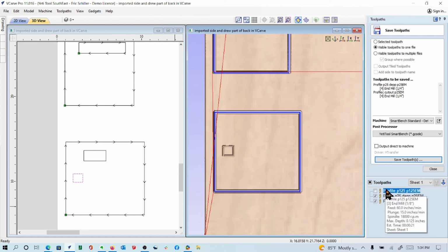So we'd have, just typically for a cabinet, drilling operations with the 5mm drill first, and then we do, depending on how we're building, the same 5mm drill for construction holes if we're going to do a screwed together cabinet, or if we're doing blind dados, we're going to switch tools, go to a bigger tool and use it for the dados and to make the tenons and to make the perimeter of the parts as well, the cutout. So this is the option that you want to use, and it works well.